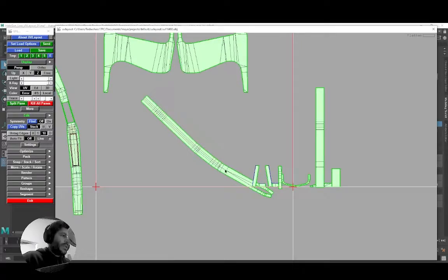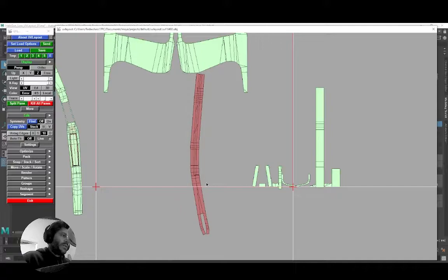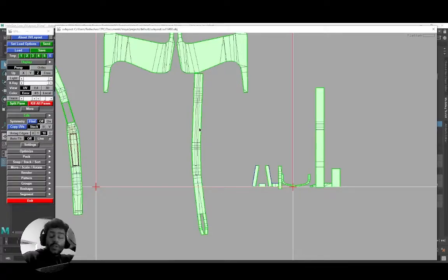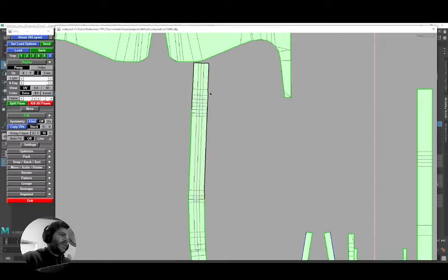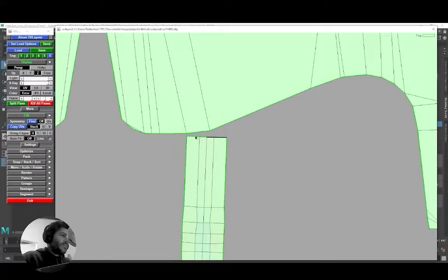So I'm going to rotate this, pressing spacebar and left click, and again I'm going to press F. And now for instance, I want to rectify some of these edges so I can improve the UV space. So I'm going to use the I function, Ctrl C, because I don't want to add the edges automatically. So I'm going to go to the edit mode, and we're going to press 0 so I can exactly mark what edges I want to rectify.